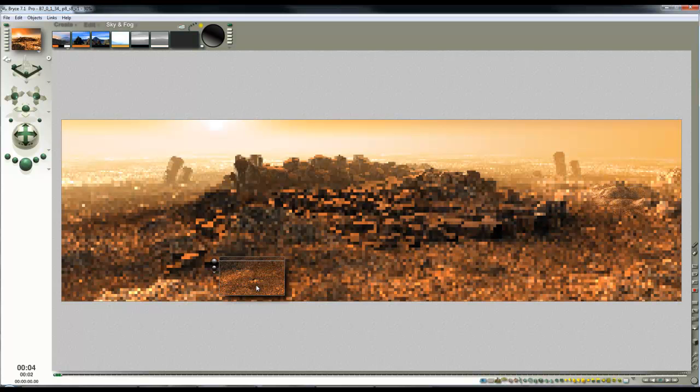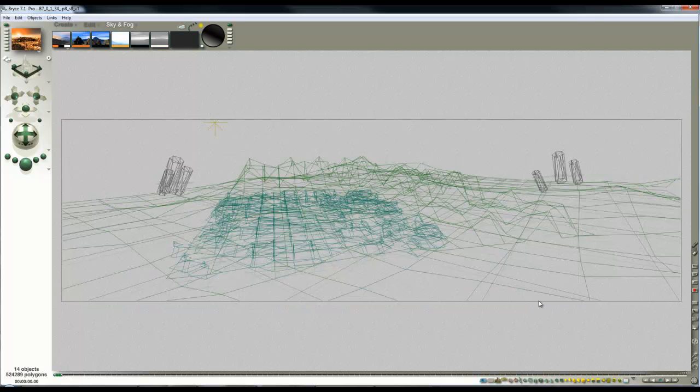As it happens, because the materials used are very noisy anyway, they've got a lot of bump in them, the noise generated by that particular rendering method will probably be quite low. Another thing to consider is these hexagonal shapes here that are a feature of this landscape have got reflection set in their material settings, and when you incorporate that with the true ambience method, it can really slow things down. And true ambience tends to favour matte surfaces without reflection, partly because it renders faster, mostly because it actually allows it to show the geometry of things. So it works better with complex geometries and fairly matte finished materials.